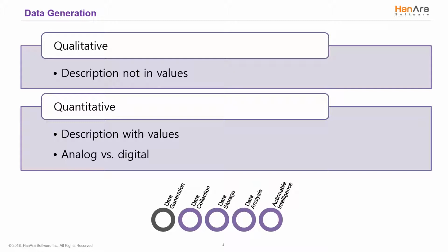The other type of data is analog, which has continuous values. The variation and slight changes are measured. Some typical analog types are temperature, pressure, and vibration. Analog tags are more accurate than digital tags, but they are more difficult to work with. For example, how do you know what a meaningful change is? How will you measure the variation? How much should you measure? There are going to be pros and cons to both analog and digital tags, and the process industry uses both to determine the current status of the equipment and systems.